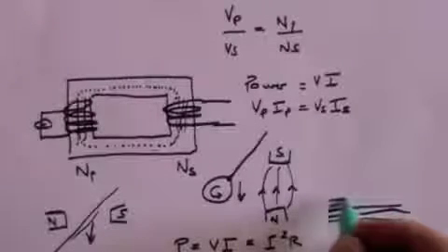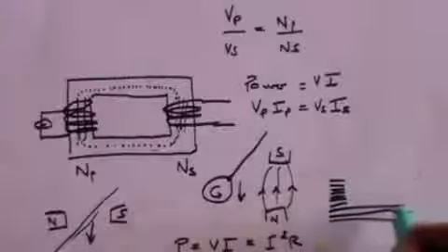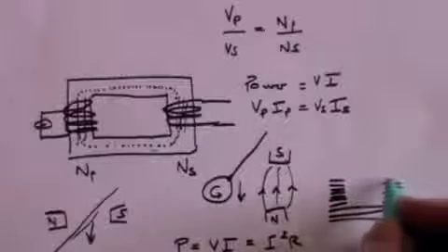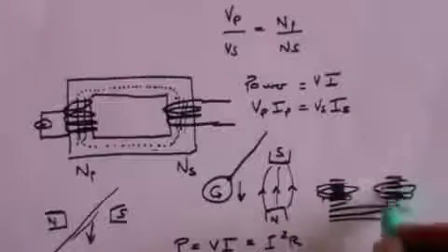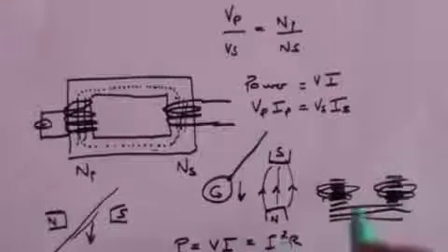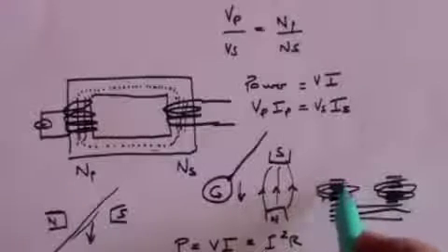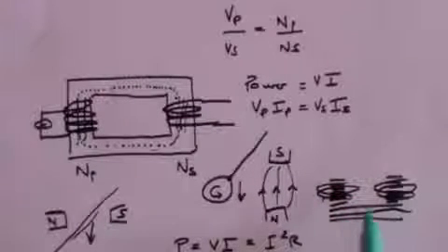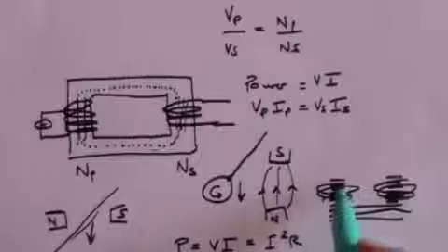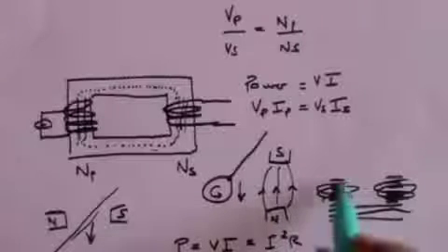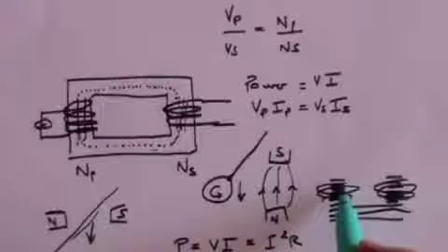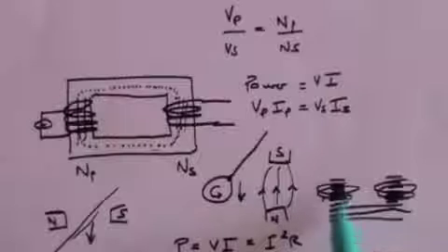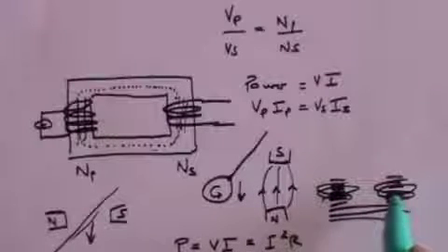So if you make your iron core like that and then wrap your coil around it, now because you've got iron and then insulator, iron then insulator, that's fine as far as transmitting the magnetic field is concerned, because these iron layers will become magnetized and will cause the layers below to become magnetized, and therefore will transmit the magnetic field.